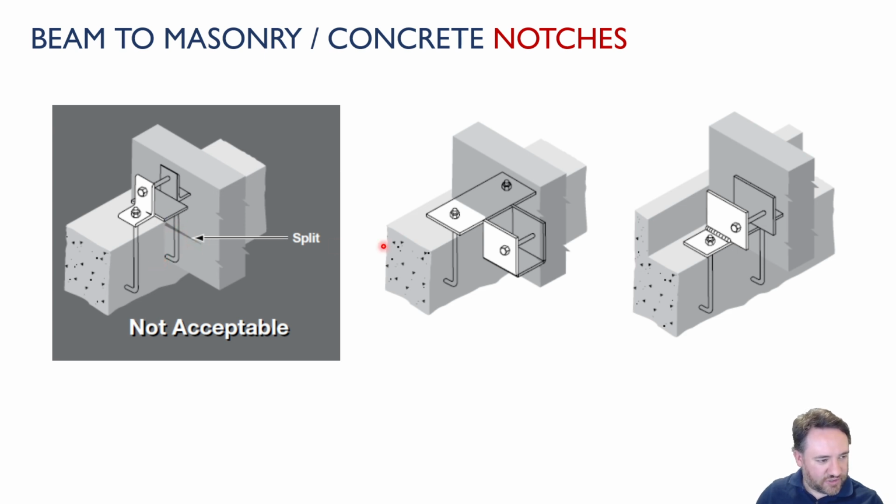Than shear notch, for example. So what I can do is design a connection where I basically have a plate that overhangs down, and that plate has a little seat so that my notched piece of wood here is really bearing on this seat. Okay, so then I have my piece of wood instead of having to deal with this notch shear.